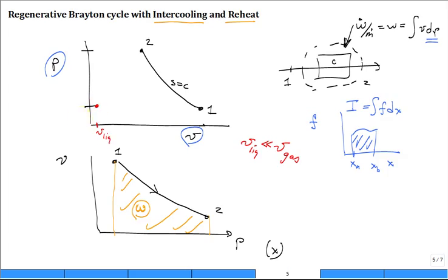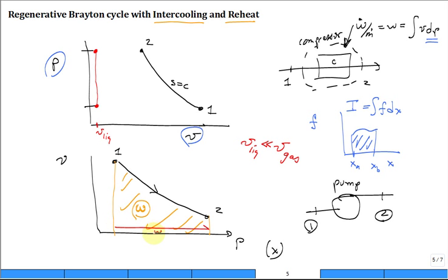And if I want to boost the pressure, like in a pump, it's not going to compress it, but I'll have a pressure increase. So this is now a pump, and this was a compressor, and I'm undergoing the same pressure change. What I find is that the work per unit mass of the pump is really small. The work per unit mass of the pump is much smaller than the work per unit mass of a compressor.